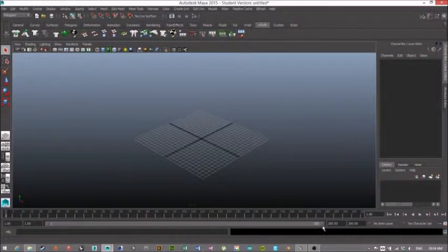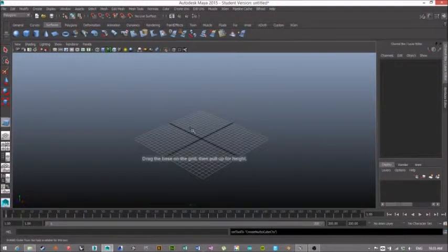When you're storyboarding, you want to storyboard your animation just like everything else. Say you're doing a sun path study. Maybe you want the sun to start where you can't really see anything, like early morning, and then it's going to take a 180-degree path over top. You probably want to do 180 frames, or at least that's the easiest way to keyframe that. But we'll get more into that as we move along. So let's start super simple, and I'll show you what keyframing does.